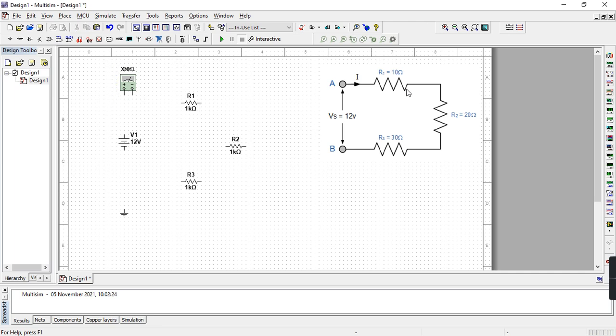Now, as we can see, the resistors of the circuit are connected in series connection, that means in every resistor the voltage is different. If the resistors were connected in parallel connection, the voltage would be the same as the total voltage. So three voltage measurements will be needed so that we can get to know the value of voltage of each resistor.